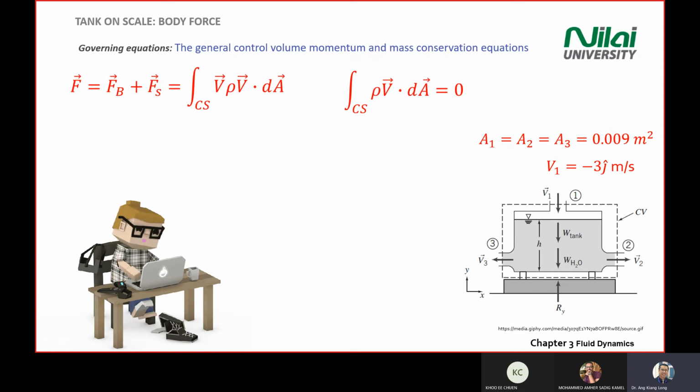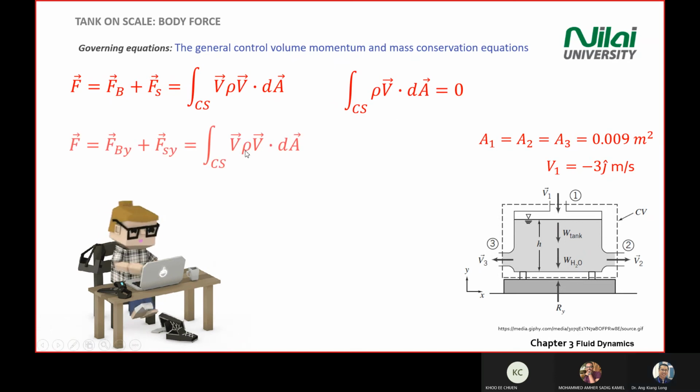Then we summarize the equation so far. For the momentum equation, we only consider what happens at the control surface. The continuity equation also only needs to consider the control surface. All right, so let's only consider the y direction.